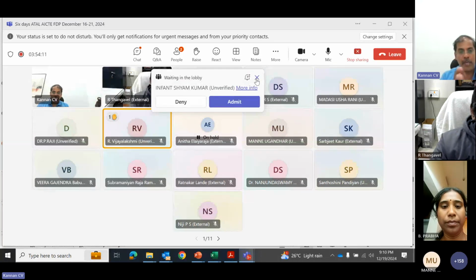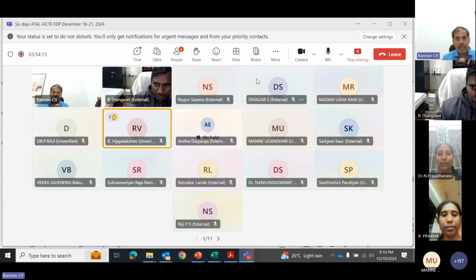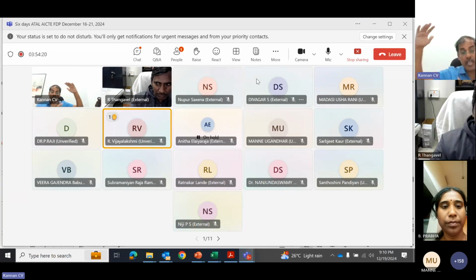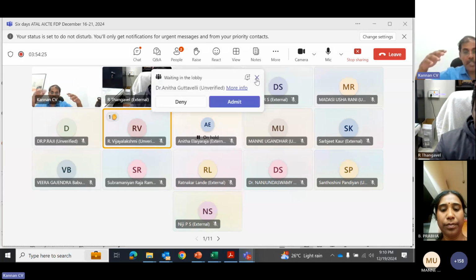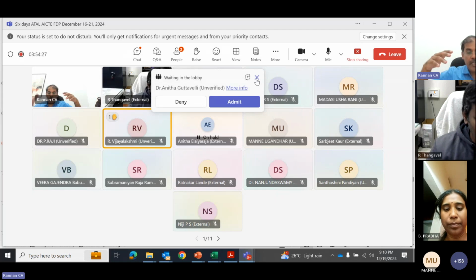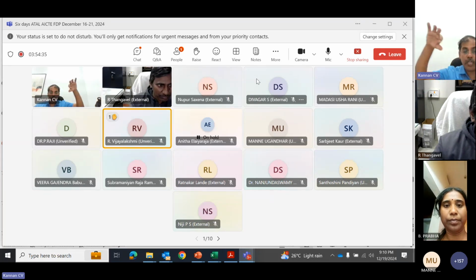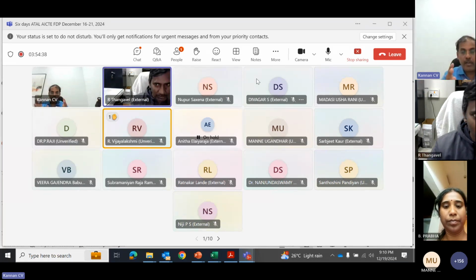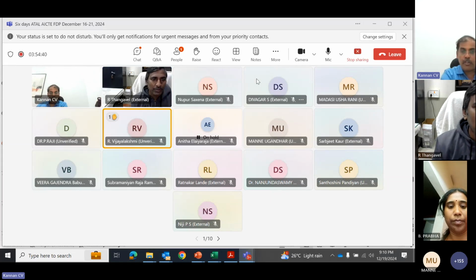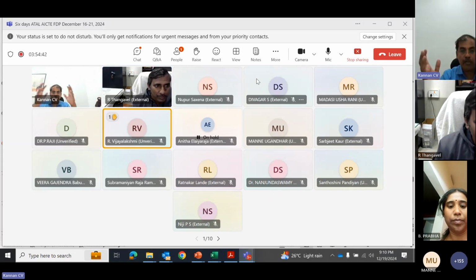Now the economic benefit of P-type is relatively lower than what you are getting in terms of efficiency. So there is more potential in N-type products. Like yesterday, the industry started with mono, this N-type also mono. Then industry moved to multi, and in the last 5 years multi is completely phasing out. Now industry is moving to mono type wafer. Even with monocrystalline wafer, industry started with N-type. In between, they moved to P-type because of the economic benefit.